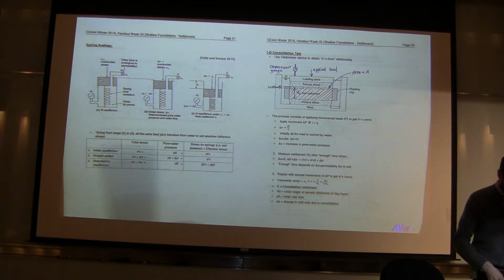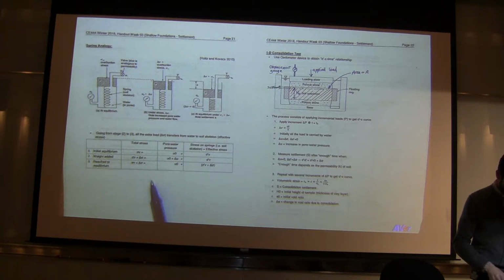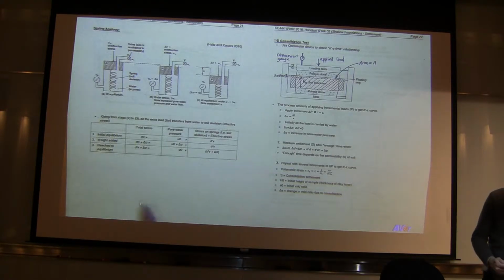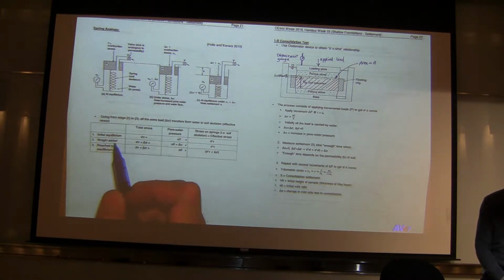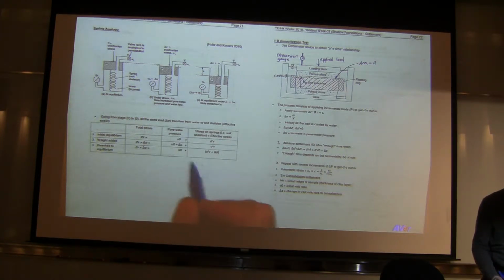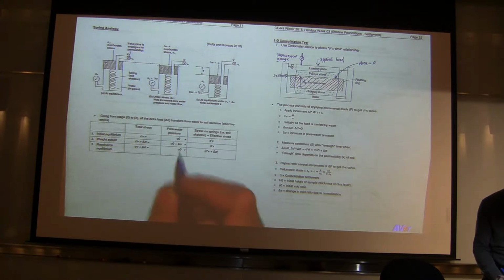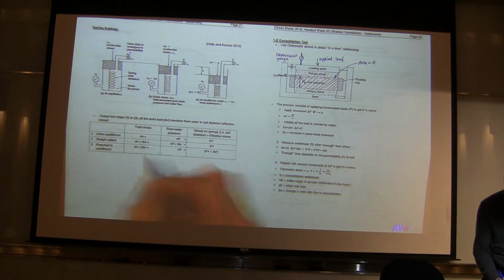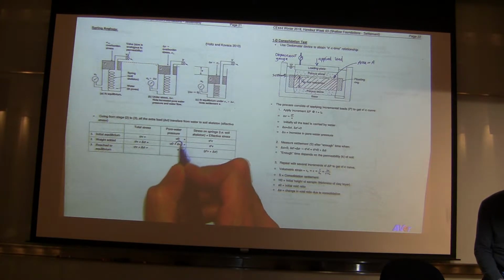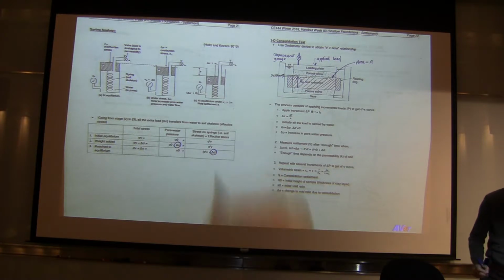So the load, initial equilibrium, then when you add the weight, and then after consolidation is over, you again reach equilibrium. So the delta sigma, that additional load, transfers from water to soil skeleton.